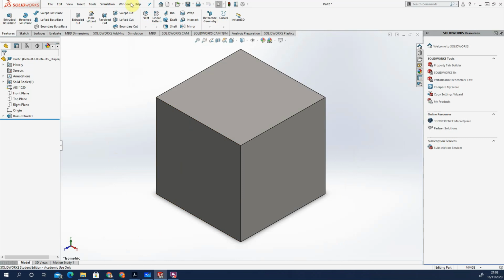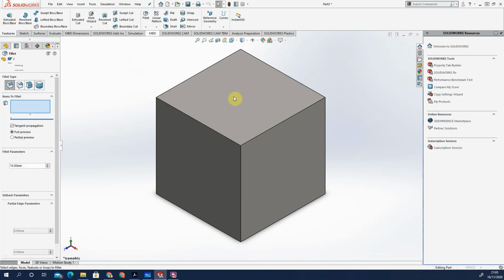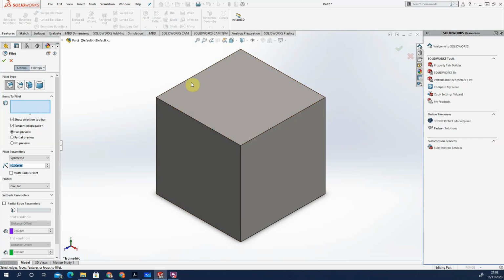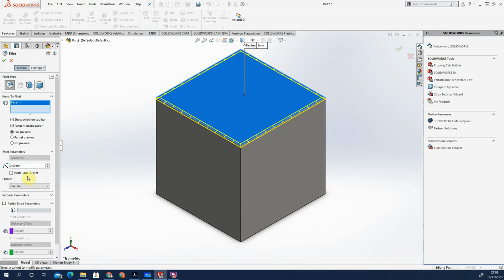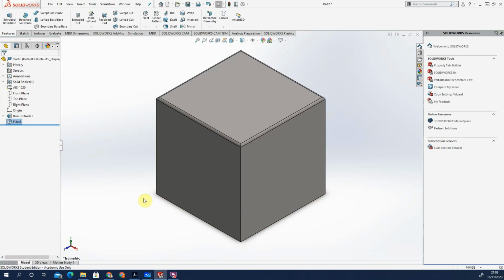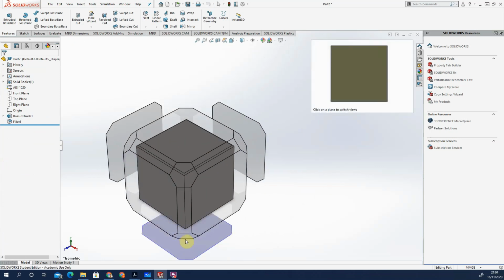So we're going to start to use some of my 3D features here. I'm going to apply a fillet to my top edge. Now I could go and select all 4 edges, or I can just click the surface like so. Just get a nice 2 mil round, just to break off any chips on those components. Control space, I'm going to do the same again on the bottom.